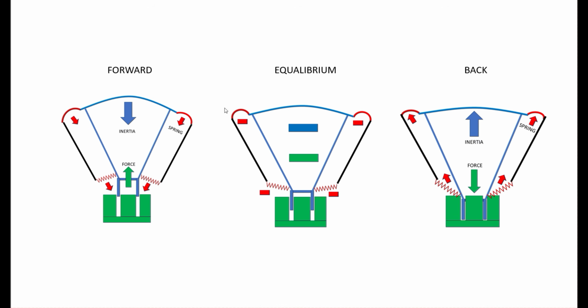And then, of course, you'll pull the speaker back to its resting position, and it'll go past that point because the drive motor is pulling the voice coil down now, and once again the springs are being stretched, but in the opposite direction, right? So there's this natural competing, oscillating spring force being pulled back and forward and back and forward and back and forward, right? And so the stiffness of the suspension will affect how the speaker behaves.